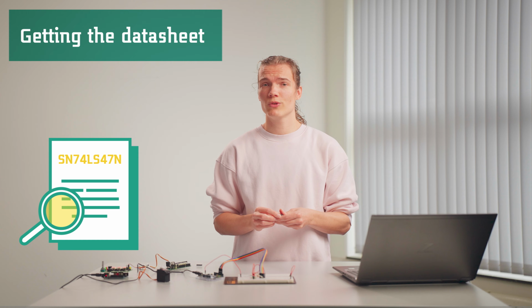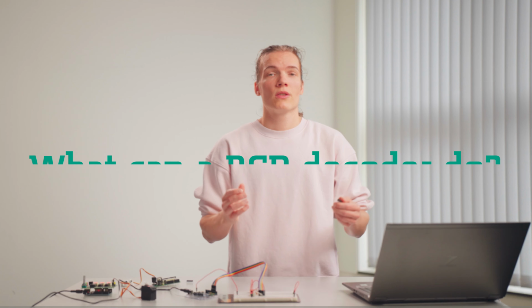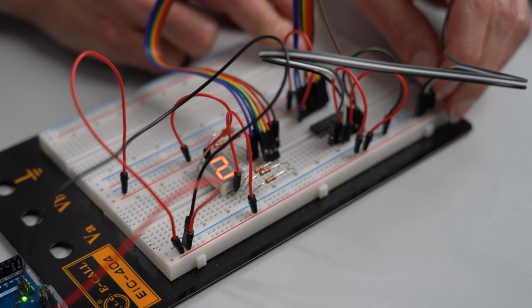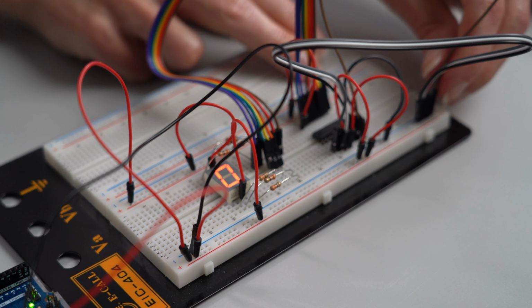But before we get into these details, we should ensure that we have a basic understanding of the BCD decoder. So what can a BCD decoder do? To illustrate this, let's consider the following example. Suppose that I have 3 7-segment displays on which I want to display a number code of 3 digits. The most straightforward way to do this would be to connect and control each segment individually.